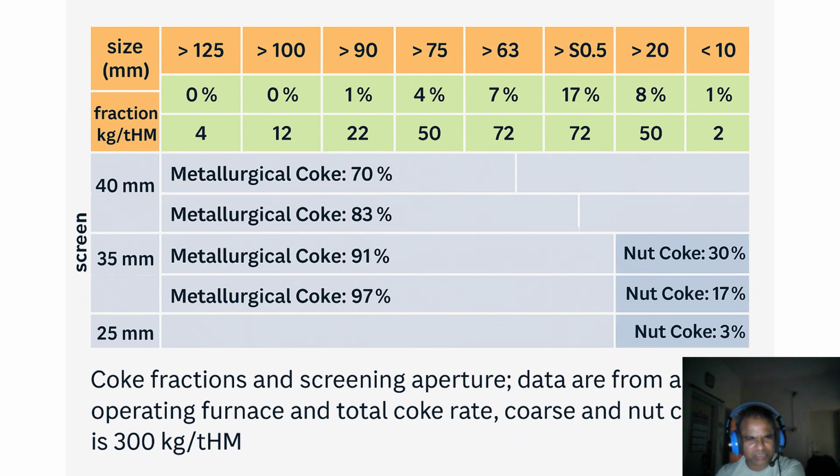And if in this process we see a generation of around 30%, once our generation of nut coke is 30% in a bigger furnace, this band is not easy to assimilate, because whatever nut coke we are putting in the furnace should be consumed in the gasification reaction only, so that our hearth can be safer and would not clog up.